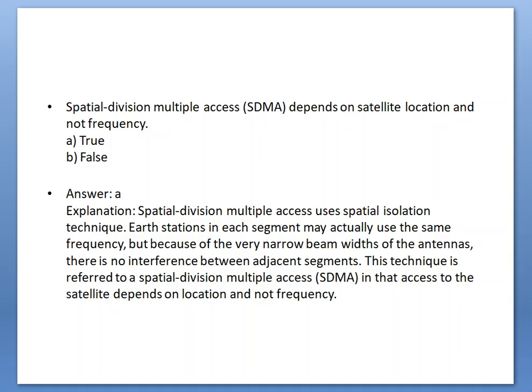By now we have discussed the topic of sample link analysis. In the sample link analysis, we detailed the link budget with a suitable example, considering a frequency of 8 GHz and a range of 21,915 nautical miles. After that, we discussed the receiver figure of merit and the received isotropic power, and we also calculated the received isotropic power based on the power, loss and temperature with respect to gain.